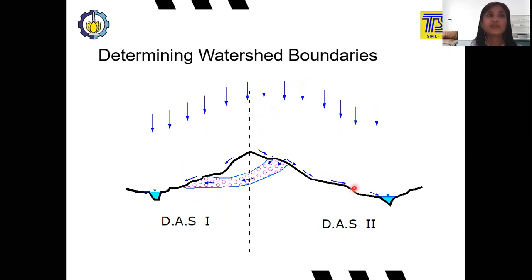That's why when you determine the surface runoff, there will be a coefficient, and the coefficient is really based on the type of your soil, or depends on the material of your surface. For example, a road with asphalt will be different from a road with only paving blocks. So the coefficient will be different between the road with asphalt and the road with paving blocks. That's because it considers the coefficient of the water going into the soil, and the coefficient of the water going on the surface. It will be learned more thoroughly in the next lesson, I guess.